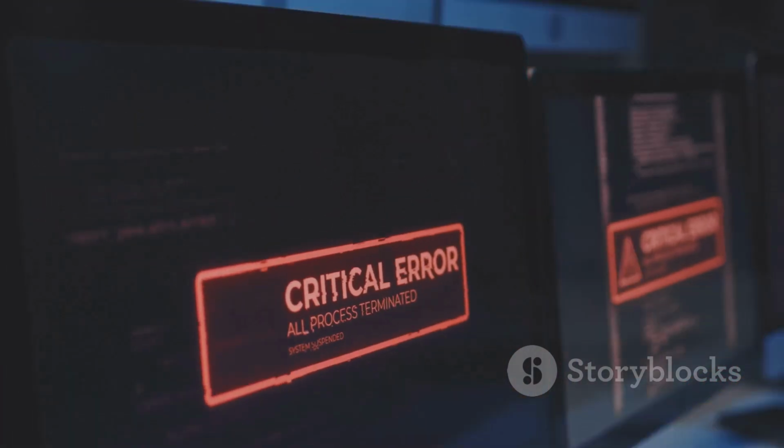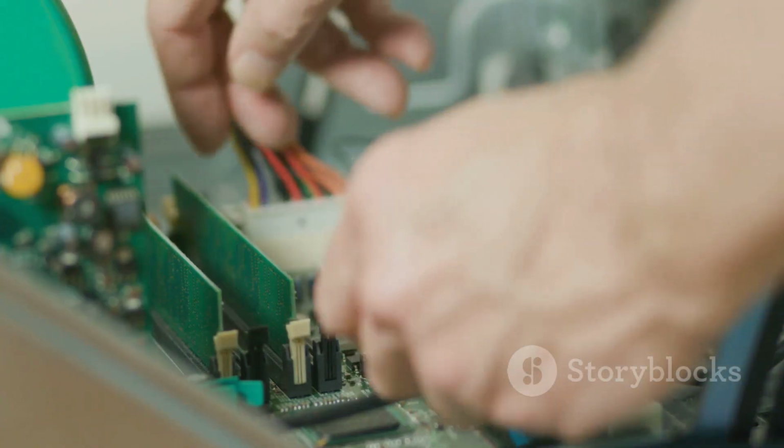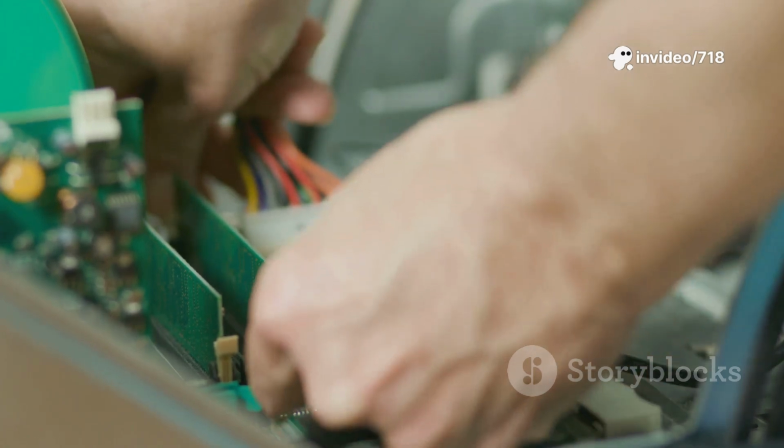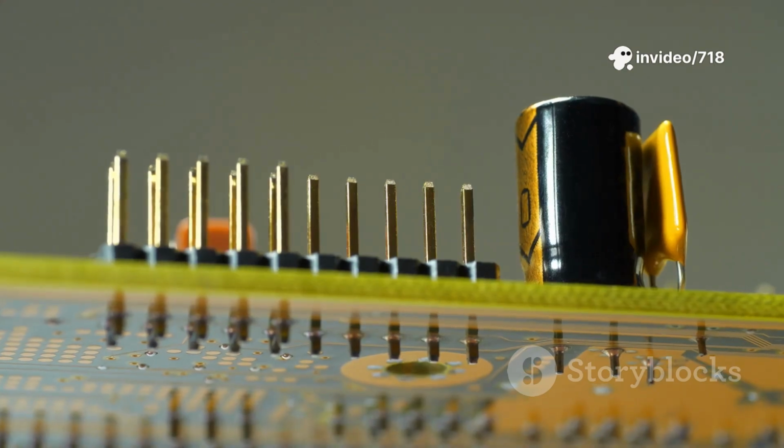Here's the catch, and it's a big one. The process of reading the data is destructive. When the capacitor's charge is released onto the bit line to be read, the capacitor becomes empty. The very act of checking the bucket's state empties it out.